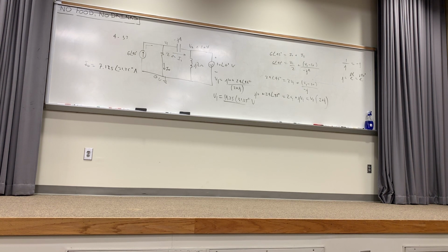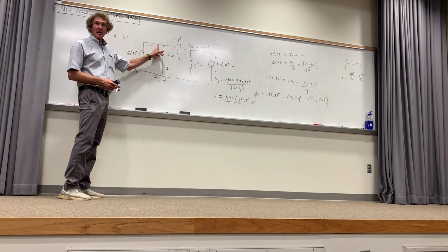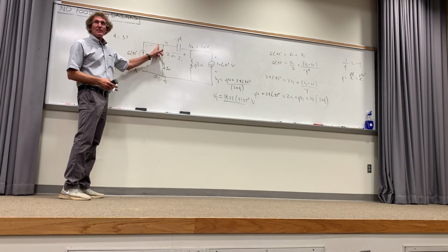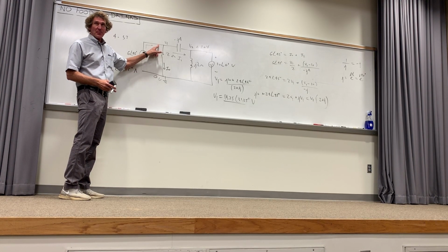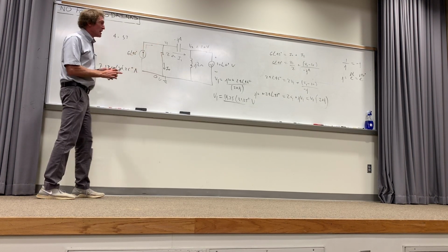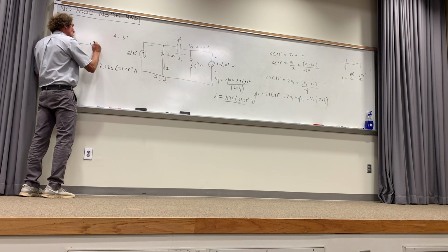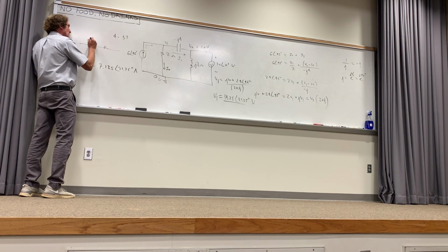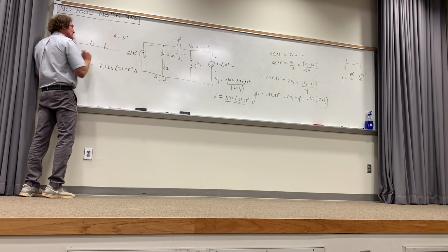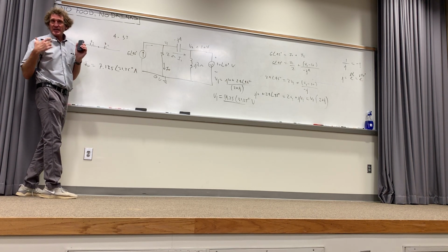So, me and someone else are having a little bit of confusion about your definition of a node. All right. Listen up. He's asking about what a node is. Here it is in a nutshell. A node is a junction, right? A point where a voltage is constant, but there are more than 2 elements connecting it. For instance, if you have R1, R2, I don't consider that a node, even though you could by definition say that. That's just a connecting point.